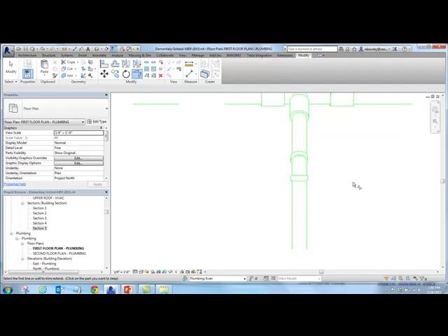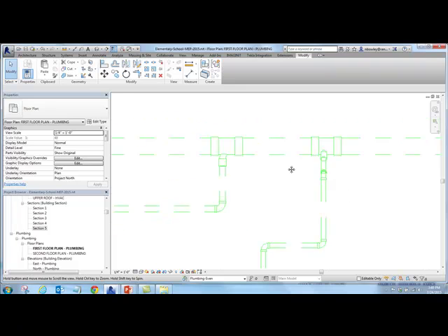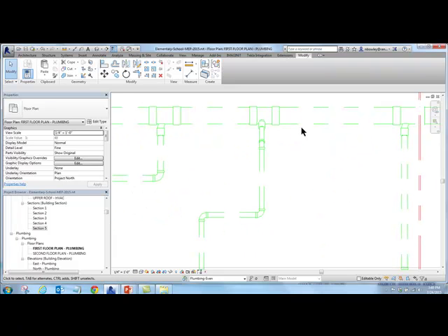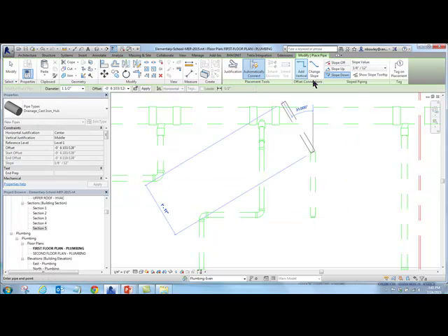There we go, easy enough. So these are real life fittings. The workaround in the past, before I knew this, was we would get close to the main, and then we would angle over to it, and then use the ignore slope to connect button wherever that is. But that's not using real life fittings.